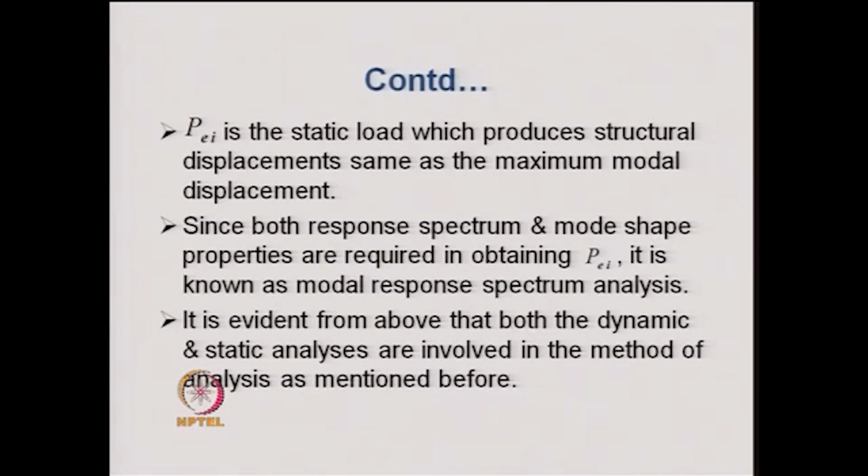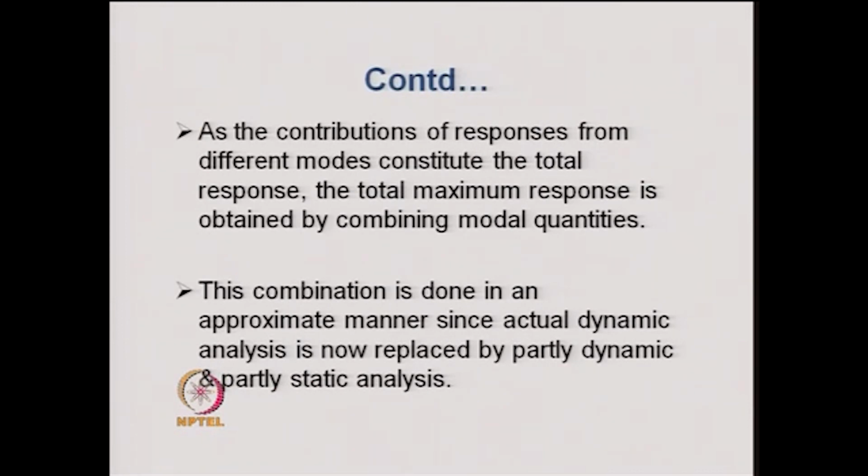And it is evident from the above discussion that both dynamic and static analysis are involved in the method of analysis using response spectrum. So, up to this part there is no approximation, it can be straight away derived using the normal mode theory, and one can find out an equivalent lateral load for each mode of vibration.